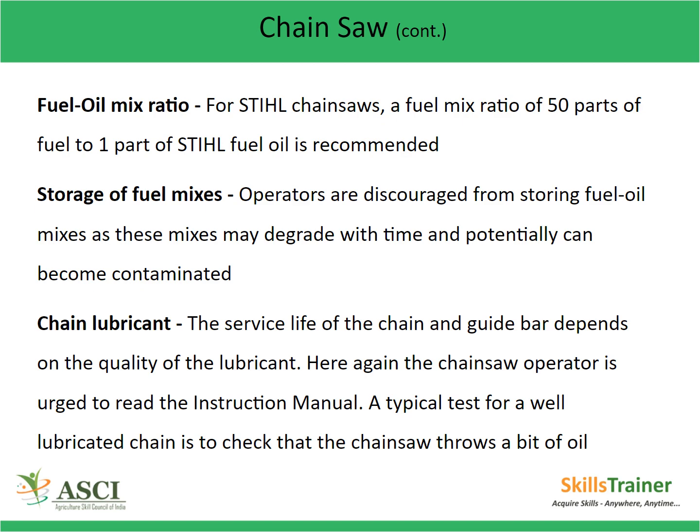Storage of fuel mixes. Operators are discouraged from storing fuel oil mixes as these mixes may degrade with time and potentially can become contaminated. Chain lubricant. The service life of the chain and guide bar depends on the quality of the lubricant. Here again, the chainsaw operator is urged to read the instruction manual. A typical test for a well lubricated chain is to check that the chainsaw throws a bit of oil.